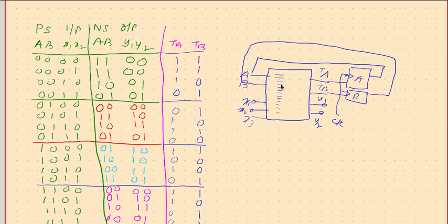Depending on what type of memory you are using, if you are using ROM, then only one type of machine is made available. If you are using PROM, you can program this once, and then the machine is available. If you are using EPROM, you can work with this table for some time, and if you want some other table, you erase this using ultraviolet exposure and then reprogram it.